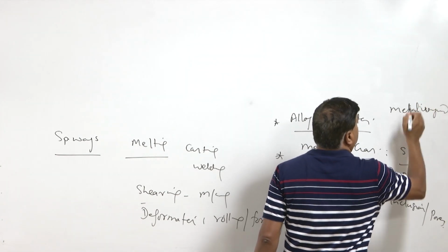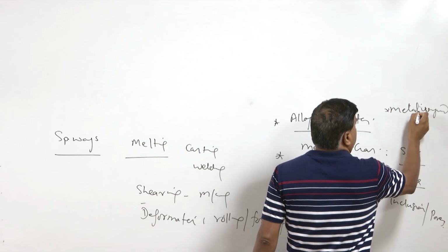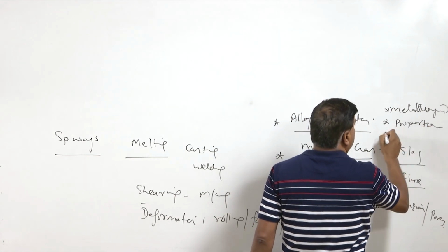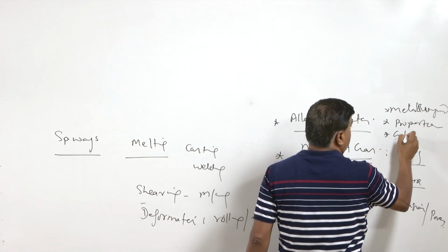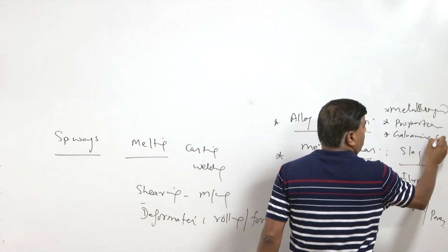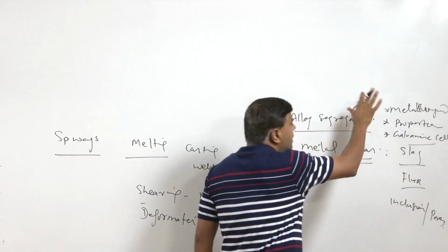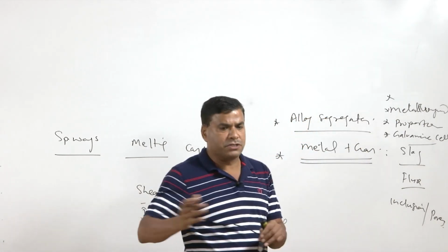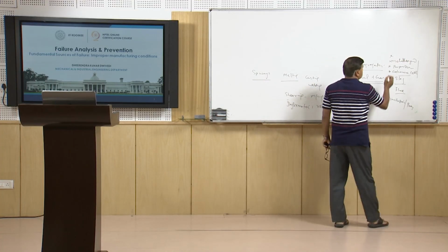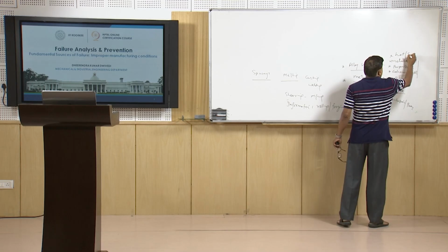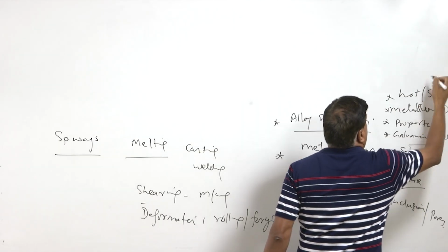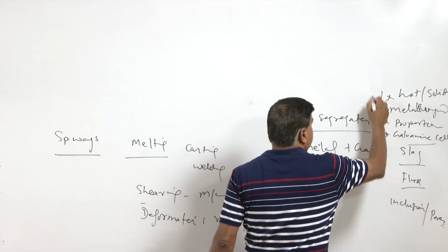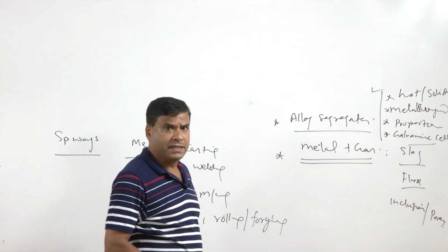Then there is a variation in terms of mechanical properties, increased galvanic cell formation tendency, so increased corrosion tendency. All these things are promoted, and increased presence of alloying elements at some locations and absence of alloying elements at other locations also promotes hot tearing or solidification cracking in the weld or in the casting. So, these are some of the undesirable features caused by alloy segregation.